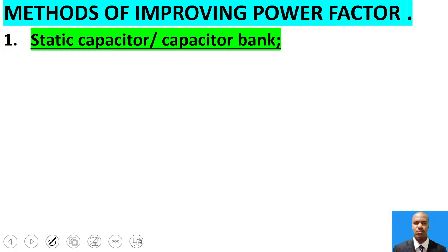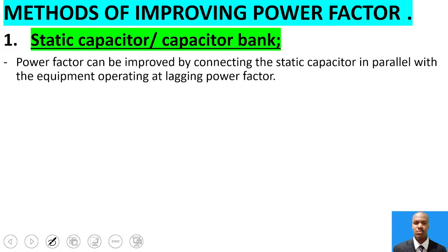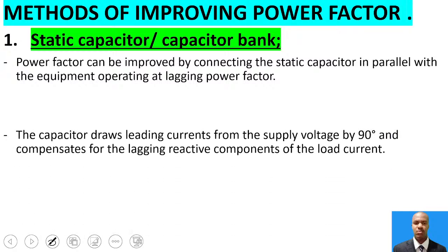And what does this capacitor do? The capacitor draws leading current from the supply voltage by 90 degrees and compensates for the lagging reactive component of the load current.